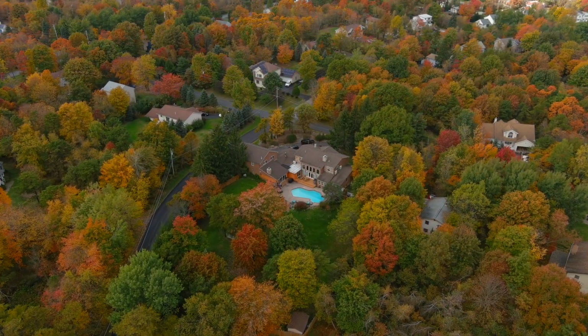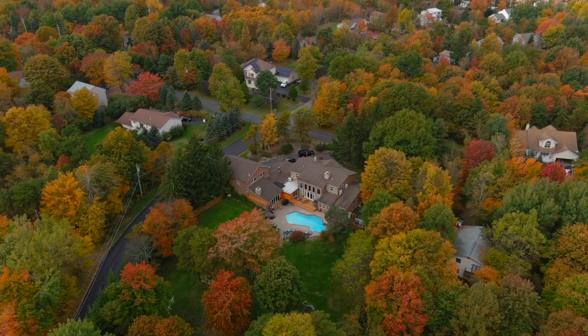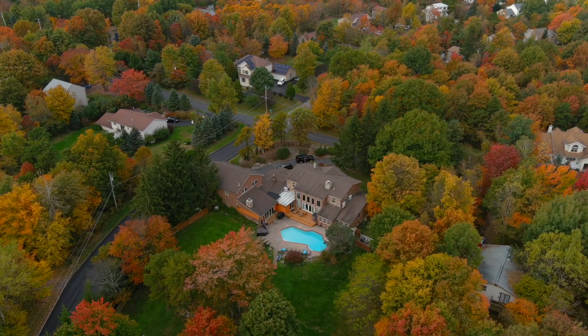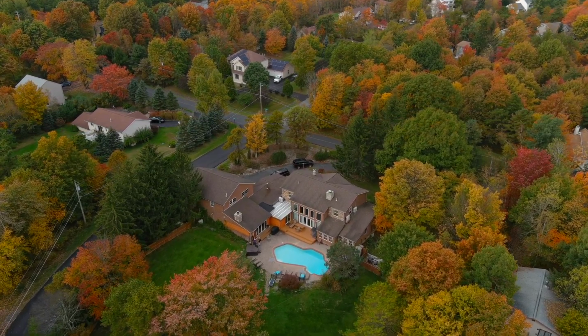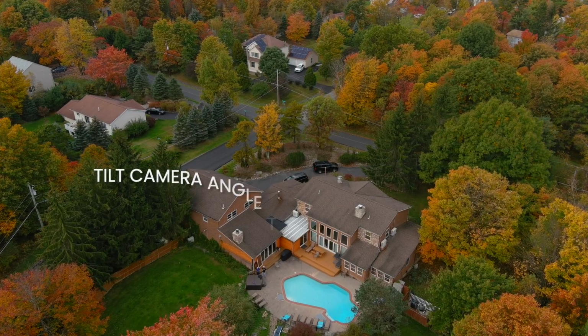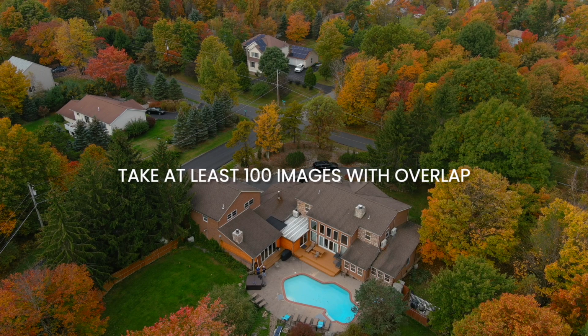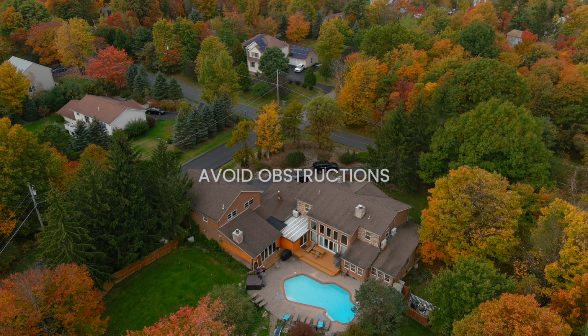The best way to learn how to collect images is to go out there and do it firsthand. You'll continue getting better at taking these photos and understanding when it's appropriate to use certain flight modes. The most important things to remember are: tilt your camera angle to see vertical features, take at least 100 images with overlap, and keep your drone away from any obstructions.